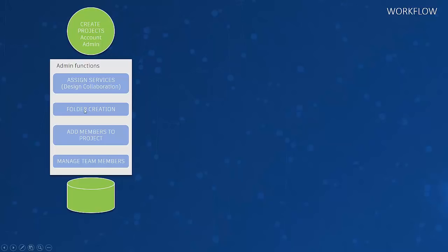So this will be the first step. We'll initiate the collaboration, and there is the option to use the high trust or the low trust workflow. So for anybody currently working in the Collaboration for Revit with BIM 360 team environment, this is high trust. This means that anybody you invite into it can access all the folders. There's no permissions to lock things down. That is still available here. You can open it up and invite all these people in if you highly trust them.